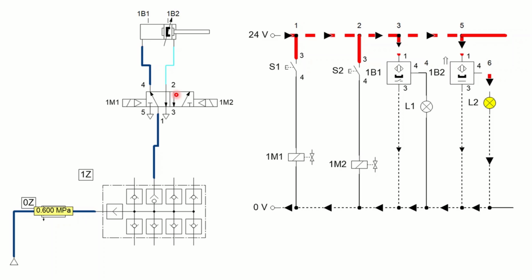So with the use of magnetic proximity sensors or any other type of proximity sensors, we can sense the position, and we can use them for systems in which we need a sort of sequence. In pneumatic basics, we were using mechanical forms of actuation, and those actuation components were linked to the position of the piston. But there were a few issues there.